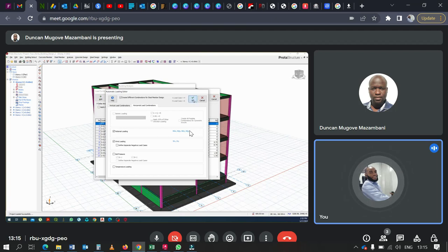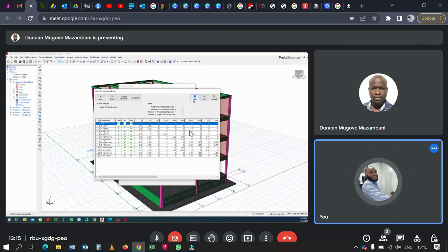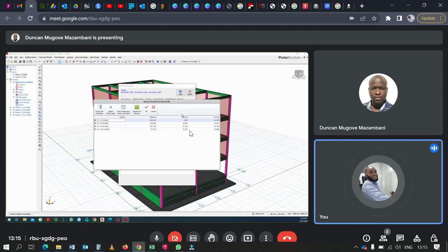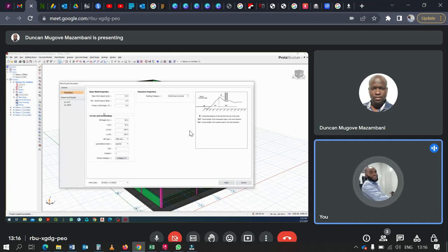Once you check that, it will take all the design codes based on wind load into this model. Then say OK, final OK. Then click on the place called wind and story loads. Now click on the place called wind load calculator. Here you can see that you have places to put your wind values.